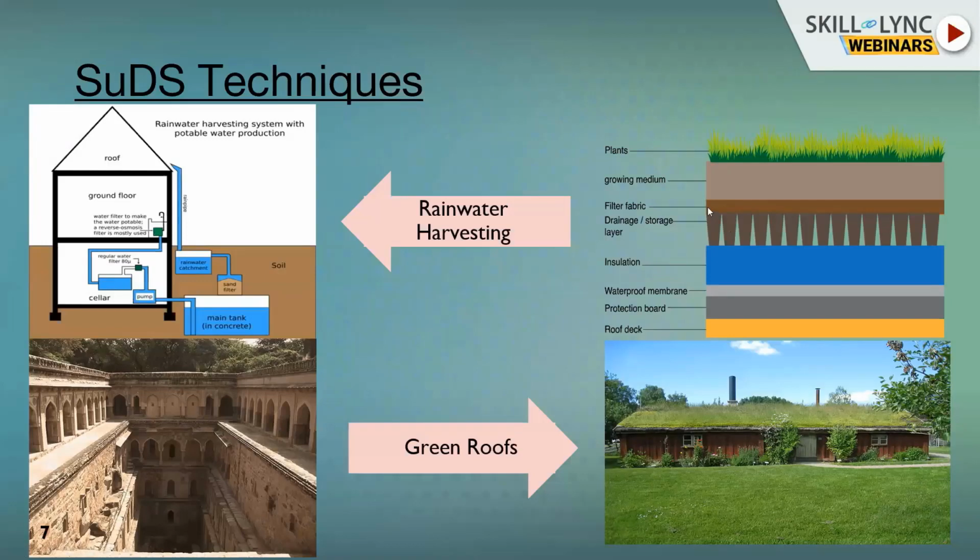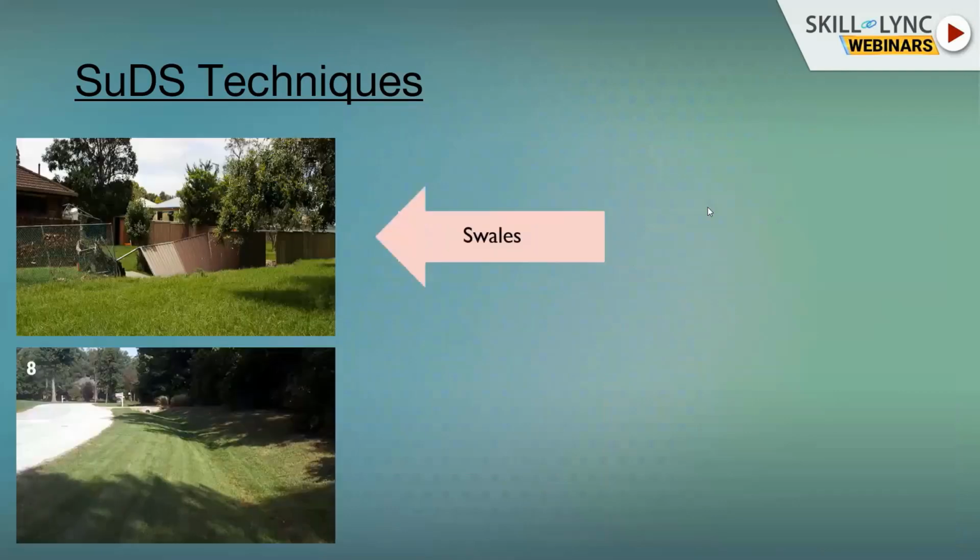So moving on to the next one, these are the swales. These you might have seen in India, but they're not designed specifically. Along the road, you have seen these vegetated channels. These are used to convey water from one end to other. Sometimes they're used for conveying water. Sometimes the water just stands here and infiltrates below the ground. So these channels can be wet or dry based on the requirement and the infiltration rates.